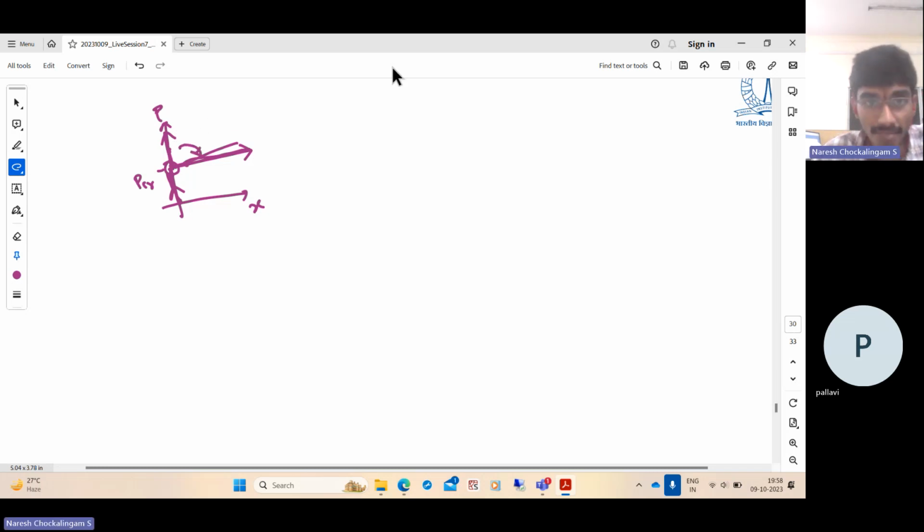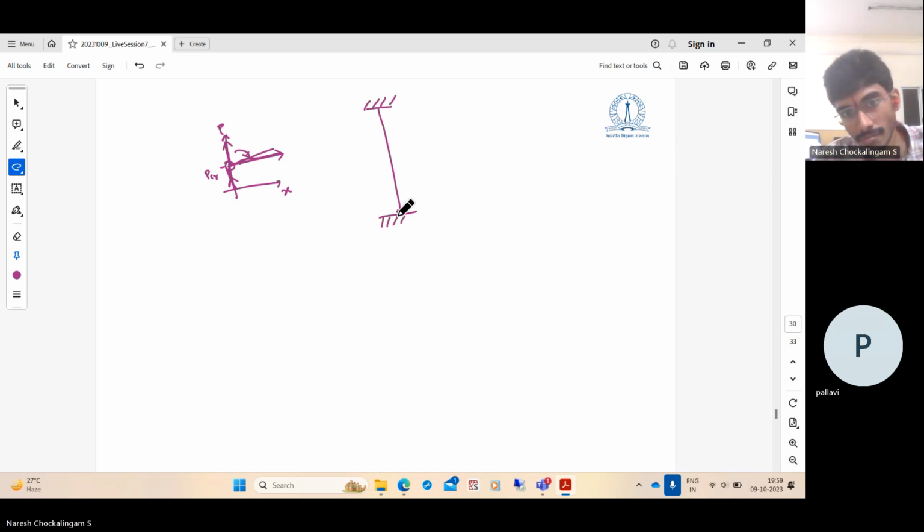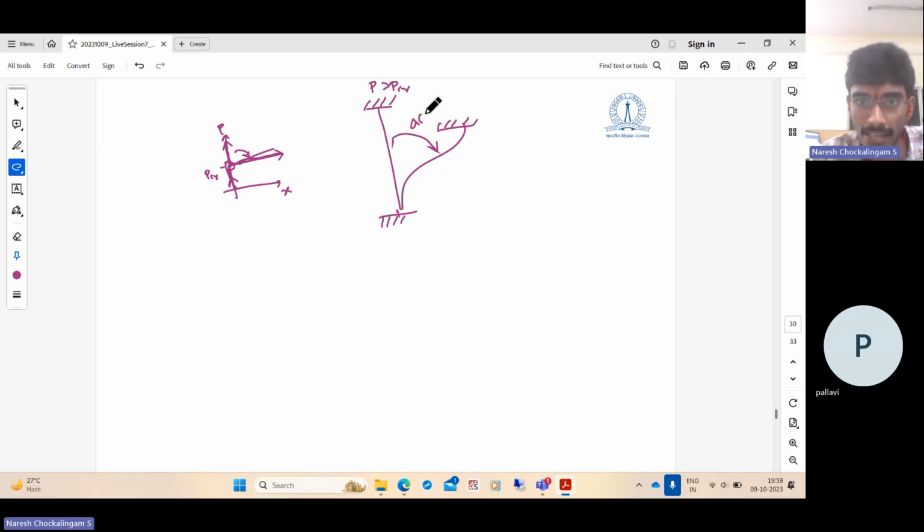So that is why stability is an important aspect while designing structures. Say you have a column in a multi-story building and the load P is greater than P critical. While we construct the column, it can remain stable. But because of some slight wind load or something, we don't want the column to buckle and go to some other configuration like this. It can still be in equilibrium, but this transition from the unstable equilibrium to the next equilibrium involves acceleration. In that case, it undergoes very large deformation in a very small time, which can damage and cause danger to life and property.